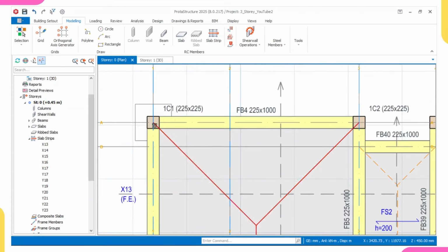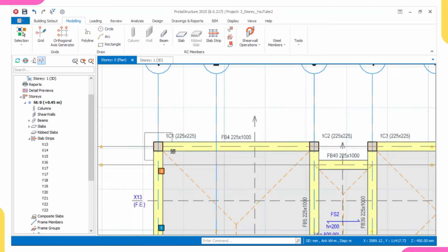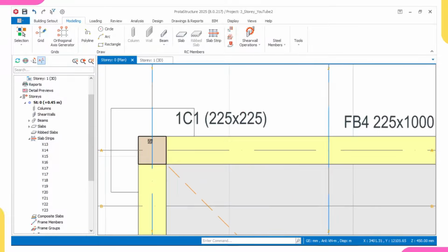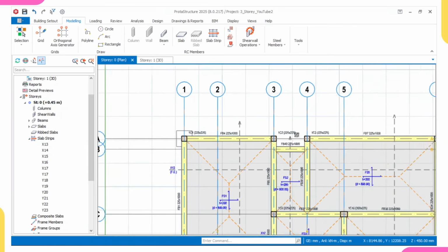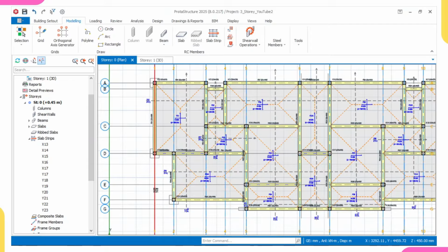But coming over to the perimeter columns, that's this column at the edge, if you see this column now, it will only spread its load around here. There is no slab around this area for it to spread its load to, so that slab will not distribute it to the soil. That means in our design, there is high probability that we'll be having failure around this edge, in fact around the perimeter columns, this column, this column, this column.